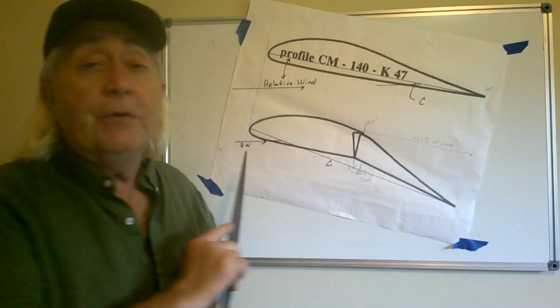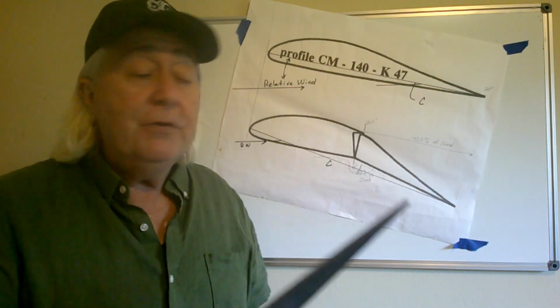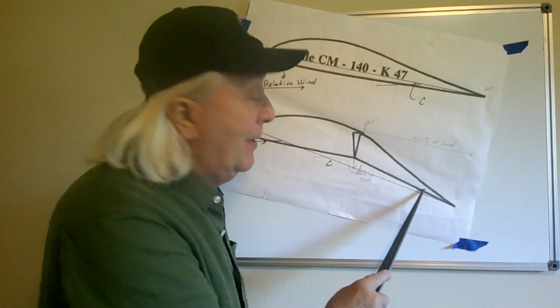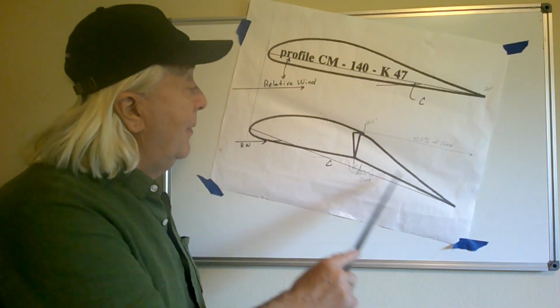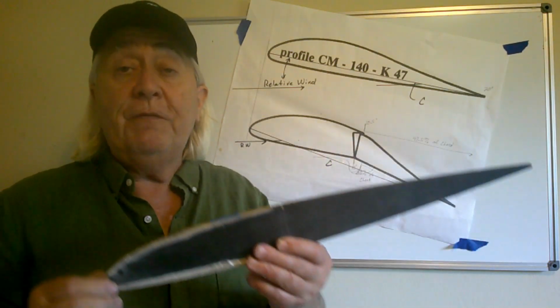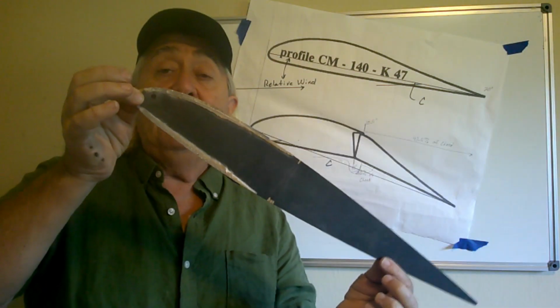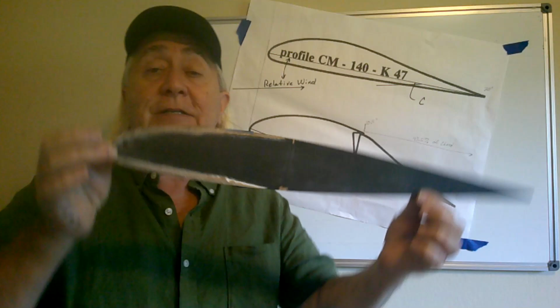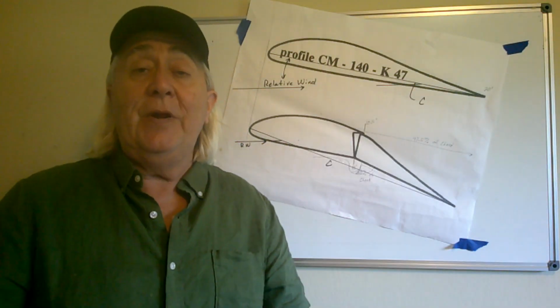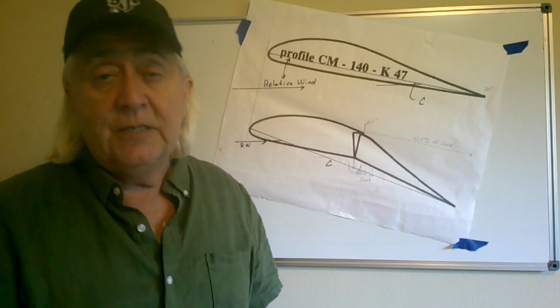This proves true for any airfoil. Any airfoil will have this problem. And I've shown you the data that says it's better to stop at 20% because you're going to lose a lot of performance as you move forward. And you get to a point up here where, oh, I'm morphing my wing, or you hinge it at the leading edge such that every time you deploy the flap, you're drastically changing the angle of attack of your wing, 2/3 of your wing. The root cause was not separated flow.